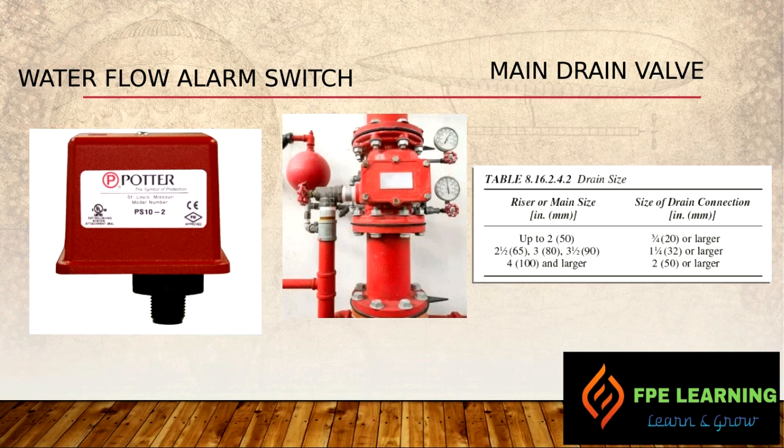So what is the need for this switch? This switch may also initiate a signal to the annunciator panel, trip the municipal fire alarm box, or give a signal to the fire pump to start. Once a sprinkler system activates, it might also give a signal to the municipal fire department. They should come to the site within 20 minutes as per the design philosophy or the local jurisdiction requirement.